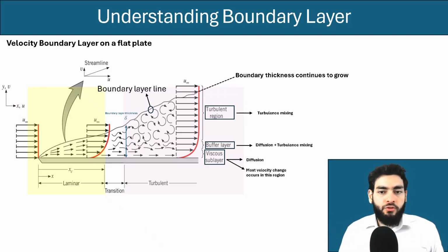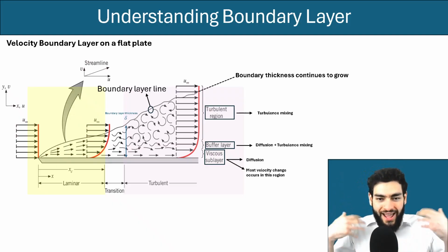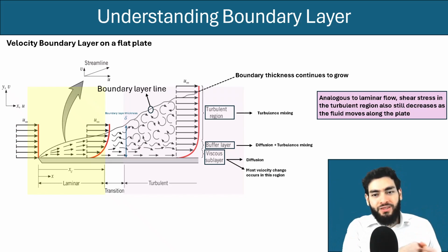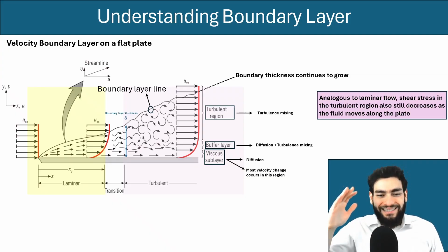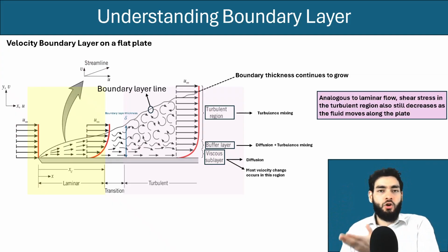So to summarize, I want to emphasize this again. Even though turbulent flow has a flatter velocity profile and a higher shear stress than laminar flow, however, analogous to laminar flow, the shear stress in the turbulent region also still decreases as you move along the plate.